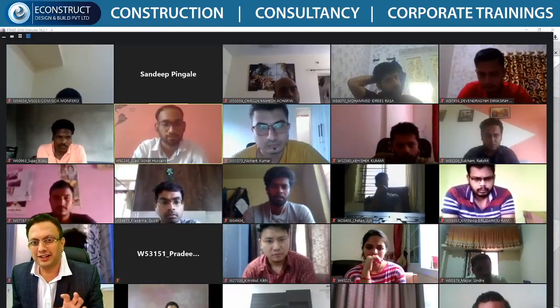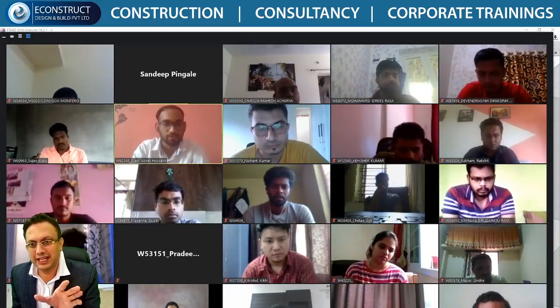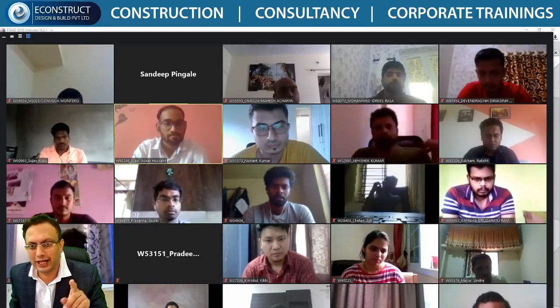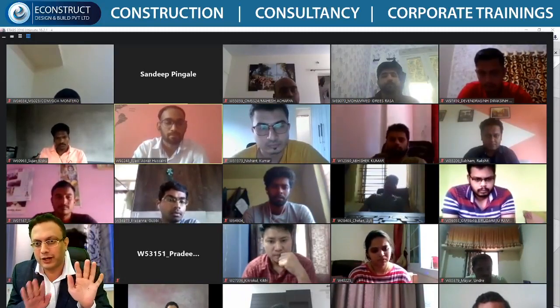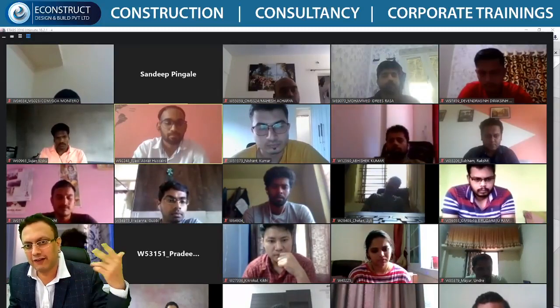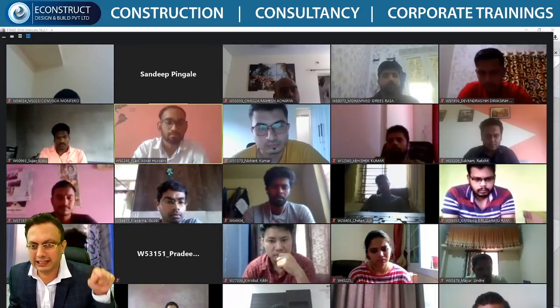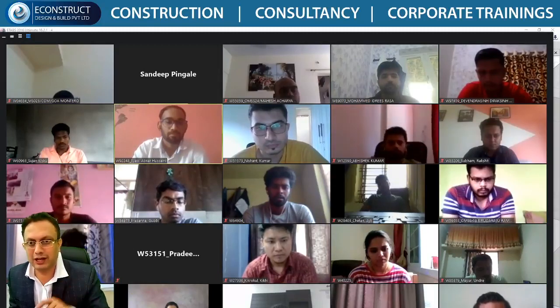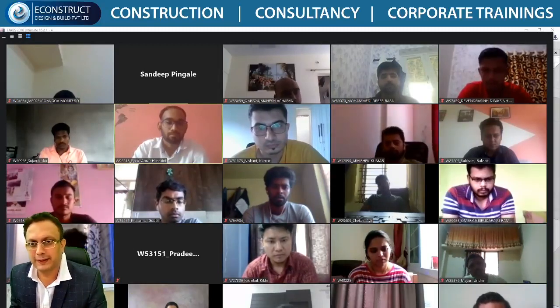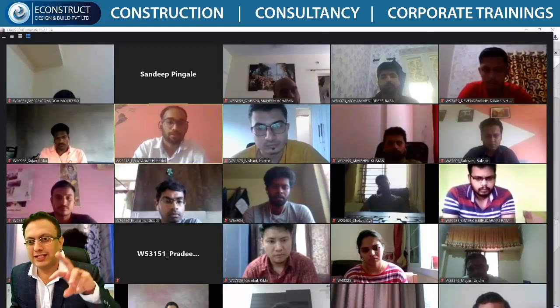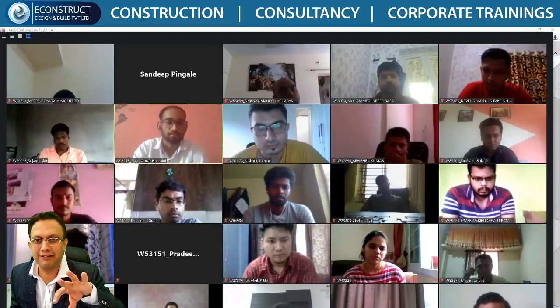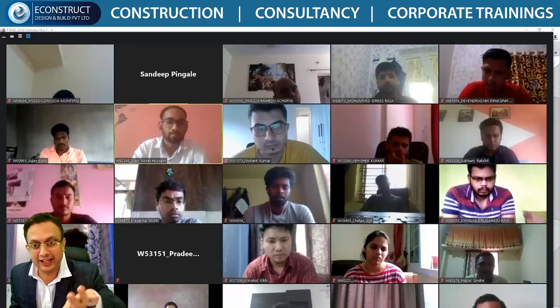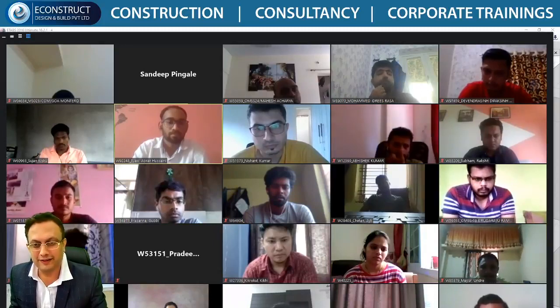On the site, what happens is initially during the casting nothing will happen, because there are props, right? Back props and all. But later on, after the casting and after everything gets over, if you are not giving that anchorage, the rotation will start. That's the point I explained a few minutes back. The structure will start acting, and acting means work will be done.